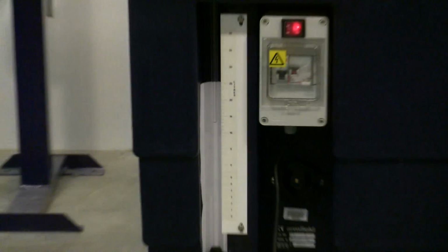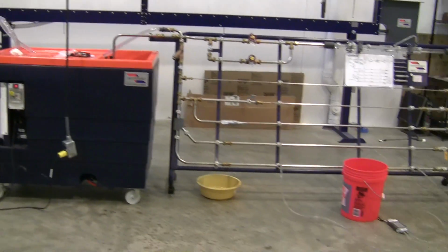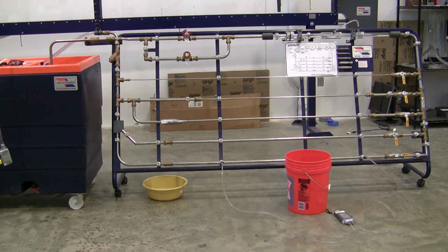All right, so now what you should have done is observed how long it takes to accumulate a certain volume. I'm going to open the plug on the wet well now. We've quantified the flow rate, and since I'm not going to be changing any of the fittings as we take pressure measurements, the flow rate won't change. If I change the position of any kind of a valve, then I'd need to re-quantify flow rate, but that's not going to be happening. Let's just tour briefly through which fittings are going to be having their pressure quantified.